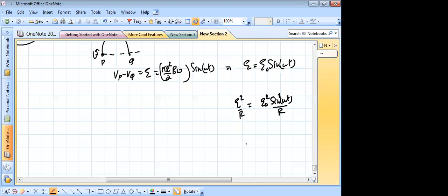So it is this thing. The energy liberated is the power integrated over time. So it will be E naught square by R sine square omega t integrated over one cycle, where capital T is 2 pi by omega. Understood, na beta? Yes.